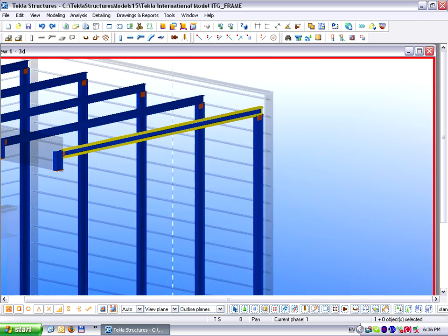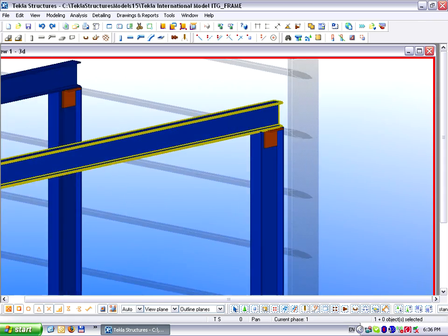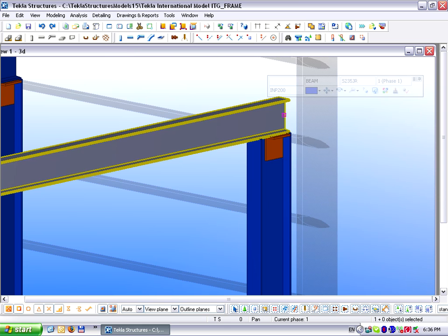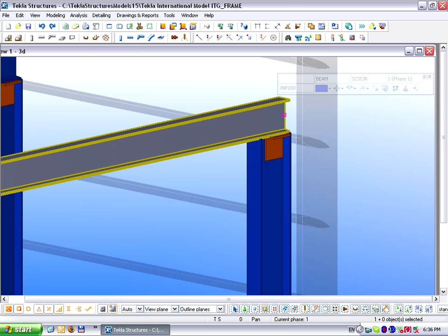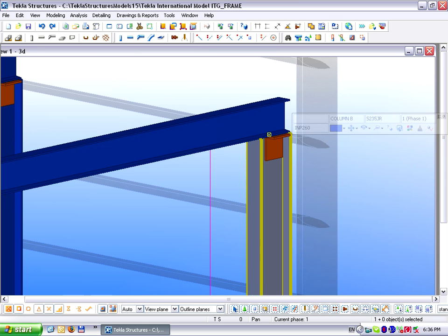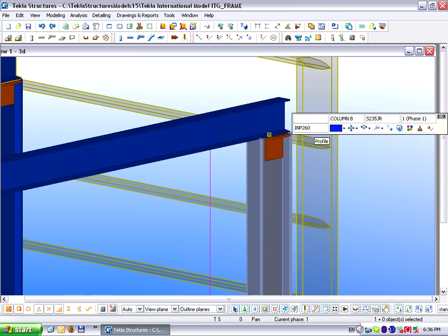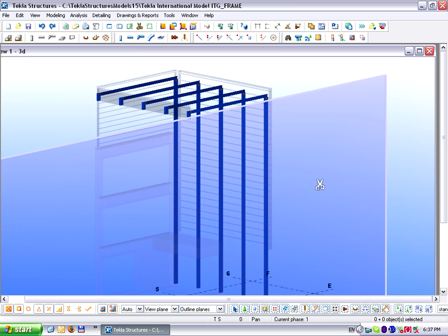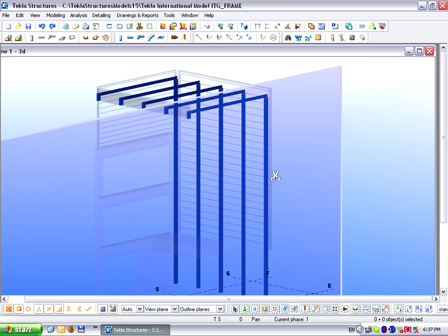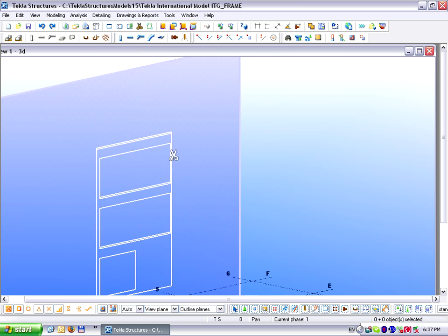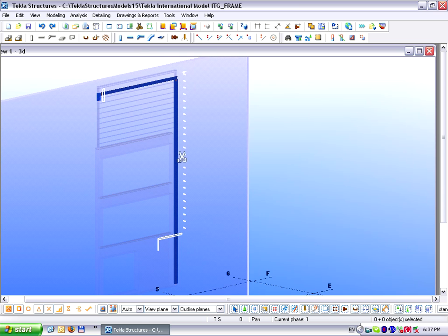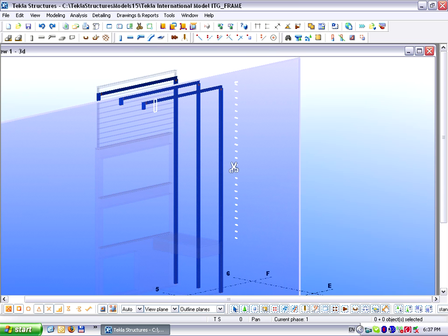They used an IFC model saved from the original ArchiCAD model as a reference in Tekla to assemble the detailed steel structure 3D model. In our scenario, this steel structure is done and we have received the IFC model from the structural engineer. We will hide first the original steel columns and beams in our design model, which were created for the design development phase, and then we will merge the Tekla structural model to the corresponding area.